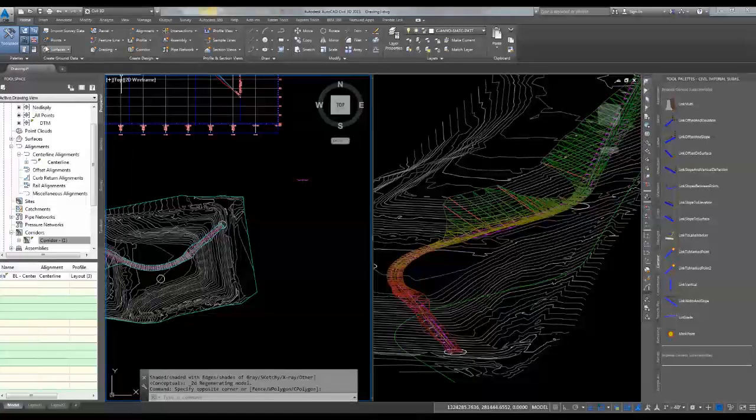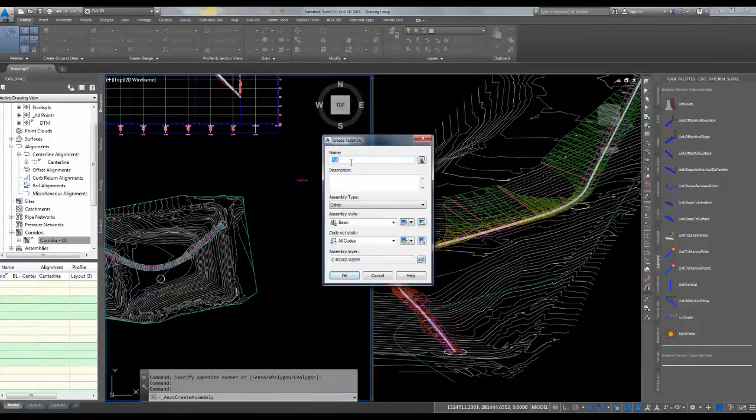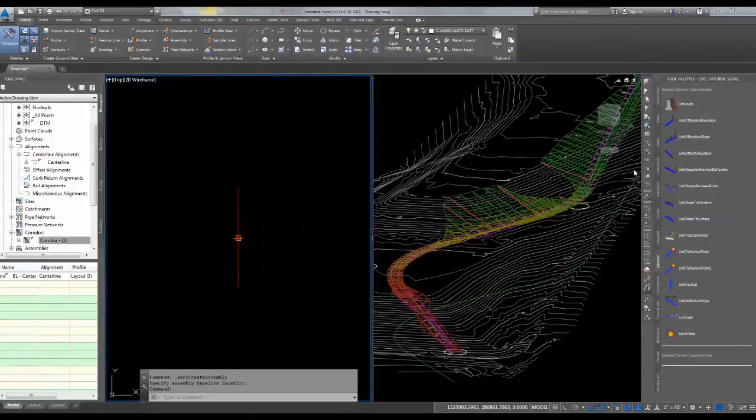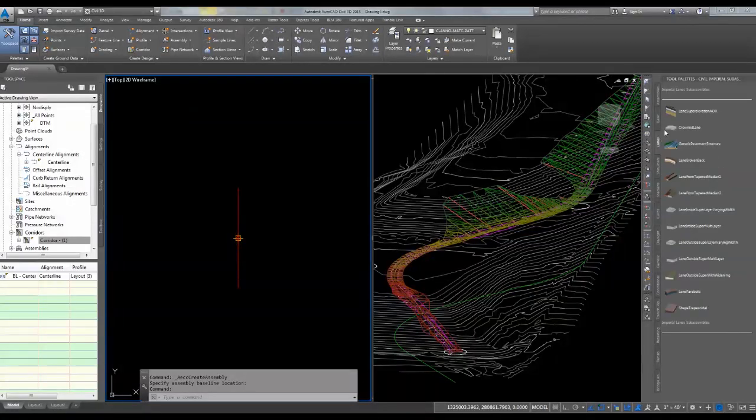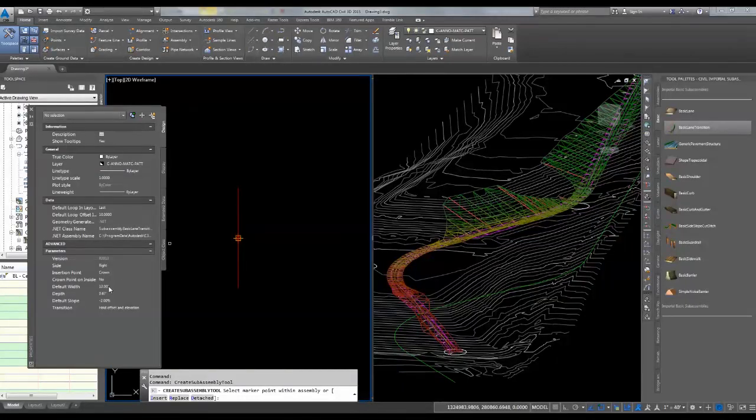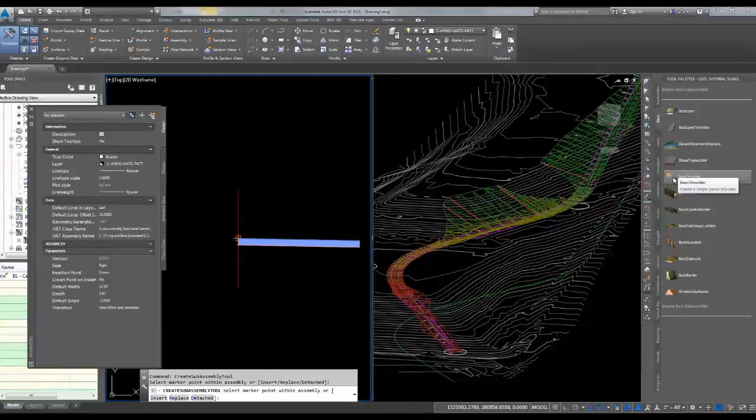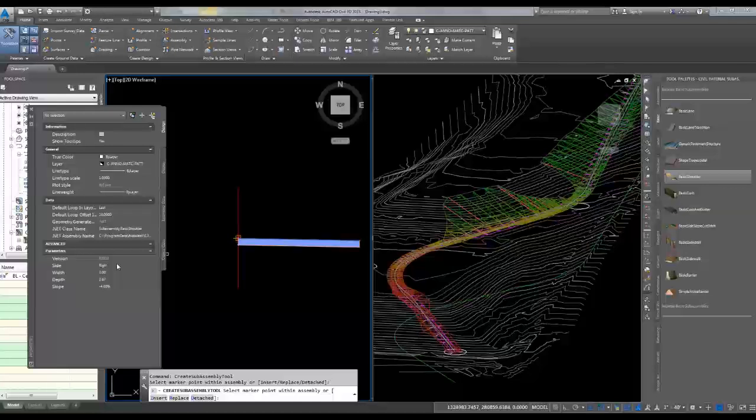So what I did was make another assembly, and we'll call it full dash 2, and I'll drop that in, and then under lanes or basic, I'm just going to use this basic transition lane. It's got the parameters set the way I want. We'll add in a basic shoulder. The basic shoulder being a 4 foot wide with a negative 4 foot slope.